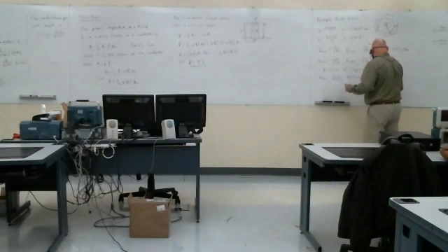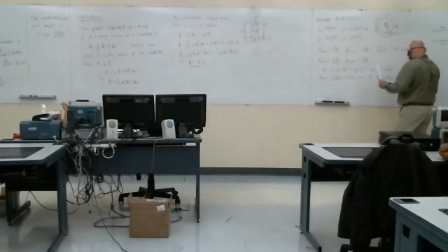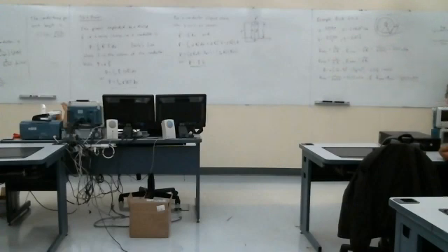So finally, R prime is the sum of these, and that turns out to be 204.3 milliohms per meter. I think these numbers are consistent with RG59 coaxial cable; this result is pretty similar to what you'll find in the tables, 0.2 ohms per meter.